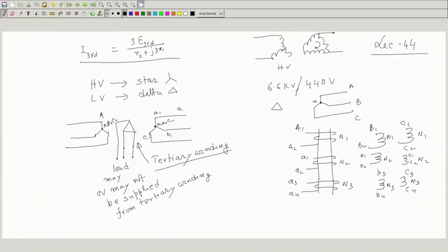And then we have very qualitatively of course discussed the importance of the third harmonic magnetizing current being present in the transformer in order to make the flux sinusoidal, hence the load voltage will be sinusoidal. I do not know whether I have a previous one there, no. Acha, let me tell you one interesting thing.